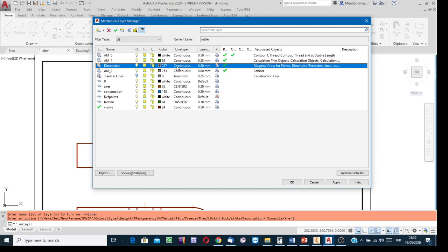Line type: extension and dimension lines are just continuous lines, thin lines, and 0.2 is the thickness. What I mean here, bringing this managing dialog box, be aware that at the layer creation stage, I have already configured the dimensioning layer. So I am sure that when I show the dimension of something, the extension lines and dimension lines will be in eggplant color, continuous lines, and 0.2 thickness. Okay, and then say OK.